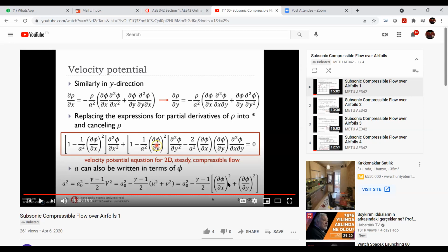And we did that last semester. The Laplace equation written for phi is a linear equation, if you remember. And since it was a linear equation, what did we do? We said we can actually combine different solutions for phi, add them up, and starting from that point, we introduced velocity potential functions, for example, for uniform flow, for sink, for source, things like that. We said we could combine these solutions by simply adding them up, because the equation that governs that was Laplace's equation, which is a linear differential equation.